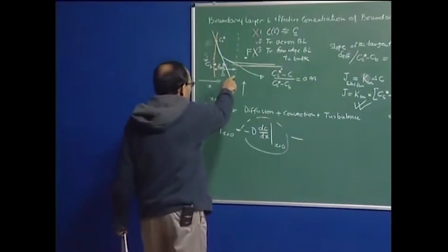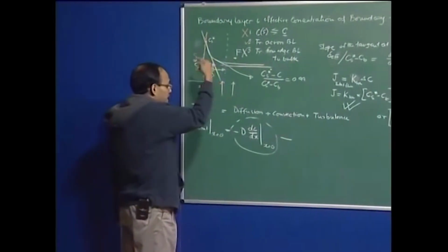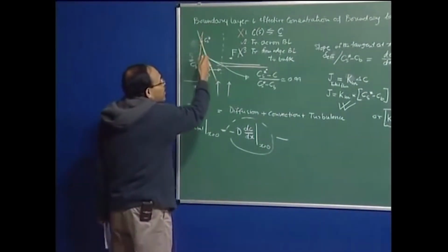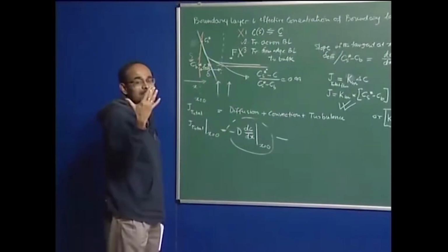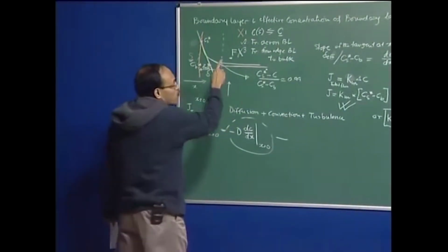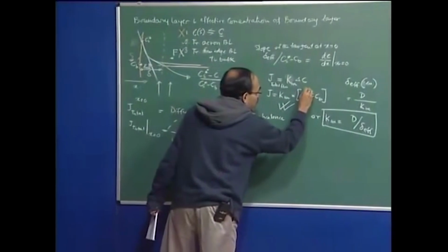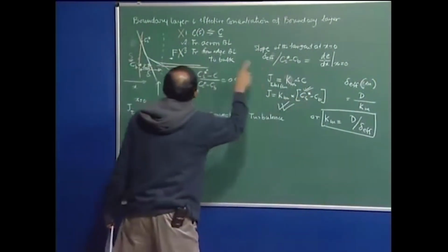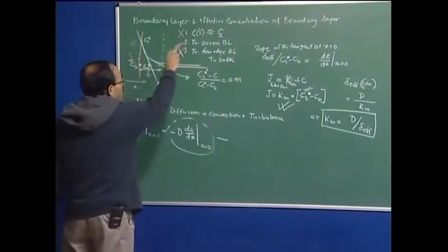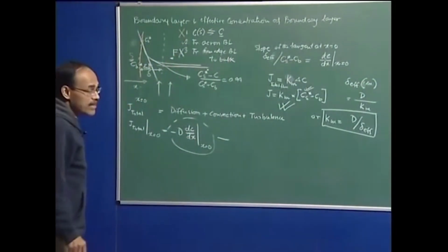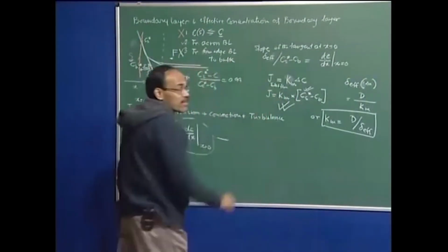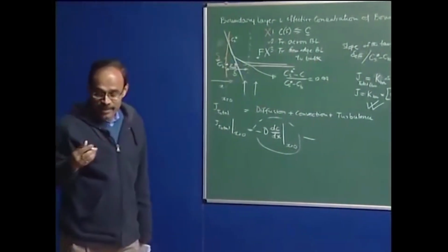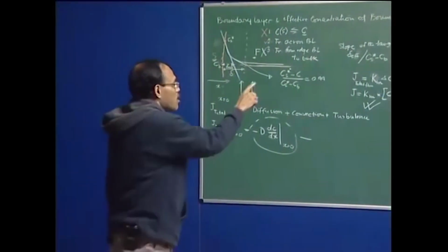So, at the temperature at which I carry out the measurements, I can find out very easily the saturation concentration level, and therefore the surface concentration term can be known. The way the surface, or interfacial, concentration during boundary layer mass transport is calculated is simply by the application of equilibrium concepts, and in this case the saturation concentration is the surface concentration.